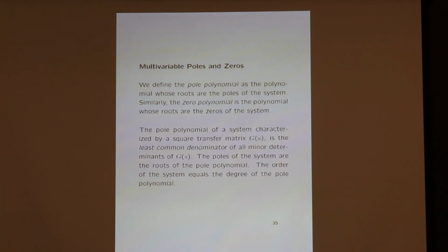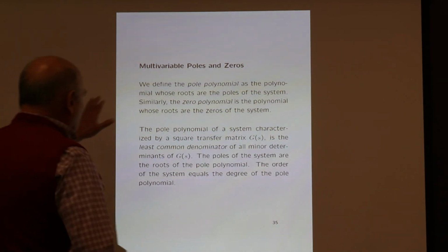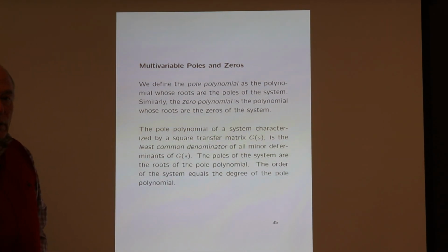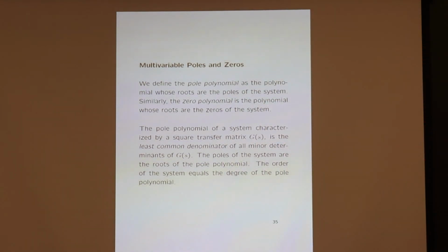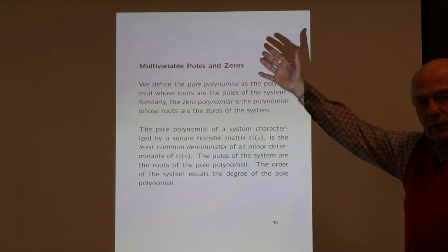The design procedure and non-minimum phase systems and so on are not as straightforward as in the single input, single output case. For the multiple input, multiple output case, the concept of poles and zeros plays an essential role in determining the non-minimality of phase of the given outputs. Some of them might be non-minimum phase, and we have to be able to compute that.